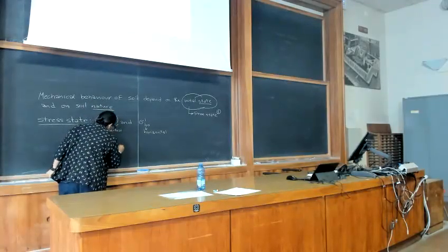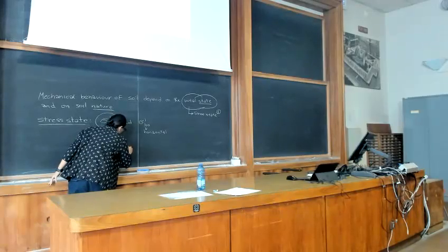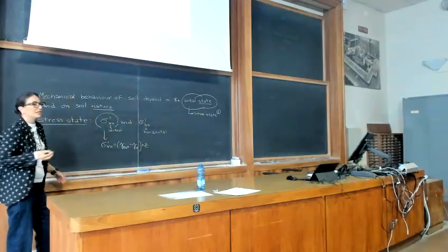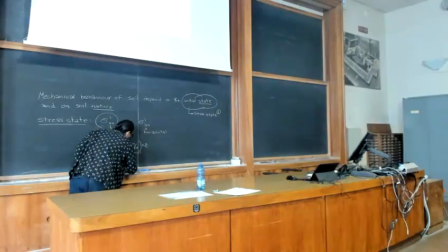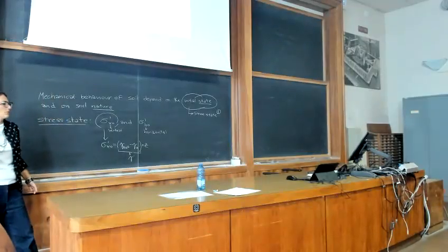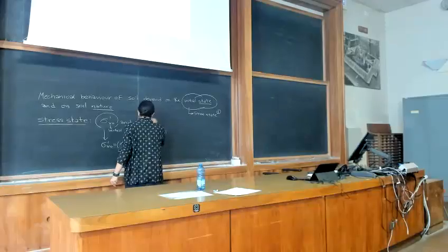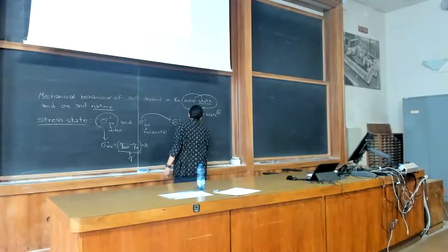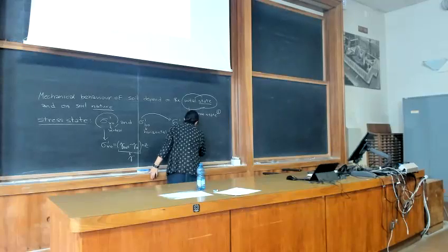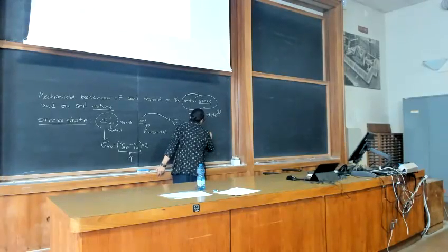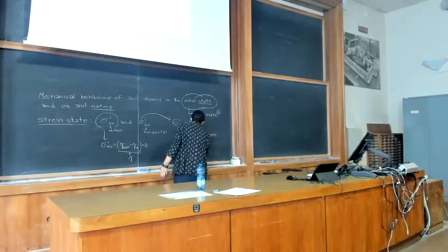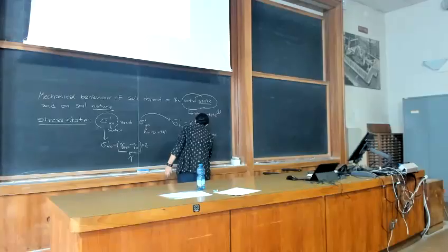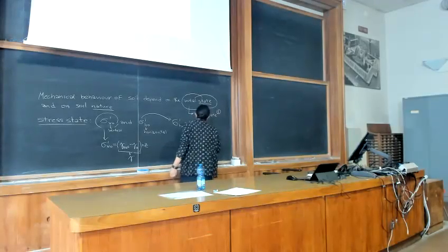Sigma dash V naught is equal to the saturated unit weight of the soil minus gamma W, which multiplies Z. This is the general formula, where this difference provides gamma dash, the effective unit weight of the soil, while sigma dash H naught is equal to K naught, the earth pressure coefficient, multiplying sigma dash V naught.